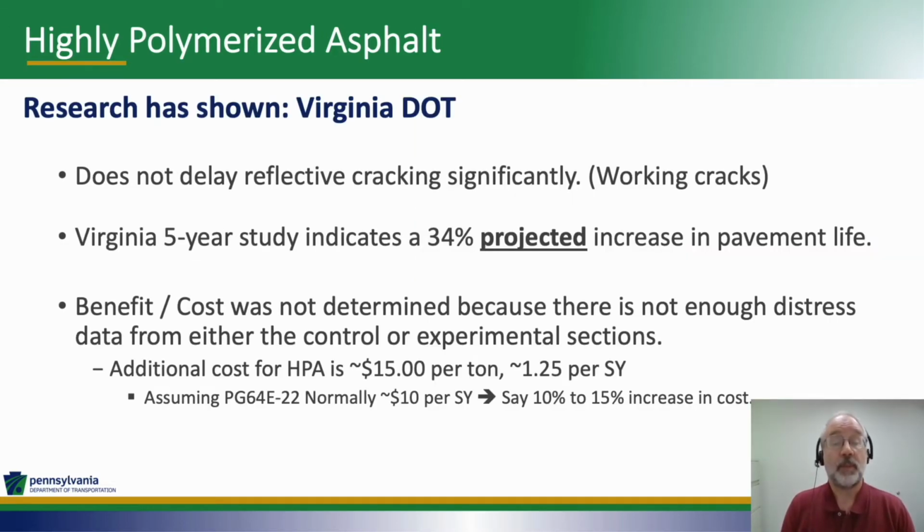The Virginia Department of Transportation did a research project recently on highly polymerized asphalts, and they found that this mixture does not delay reflective cracking significantly. There was a bit of a hope that this mix would do that, but pretty much nothing you do really affects working cracks. They're going to come through no matter what. So you still need to fix them. You can't just pave them over, even with this mixture.